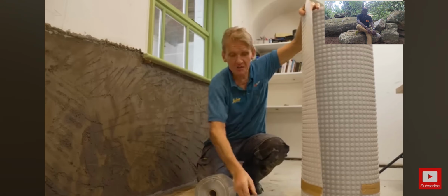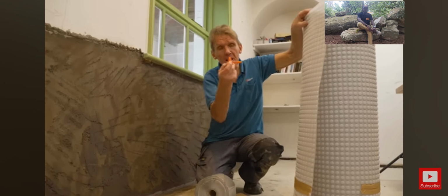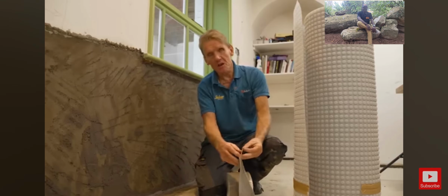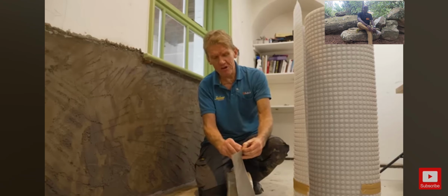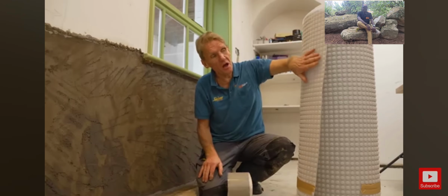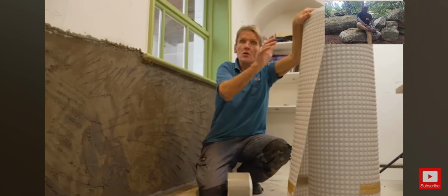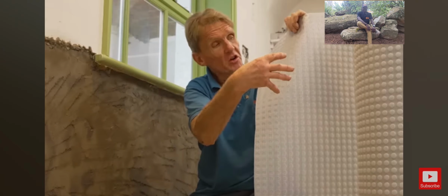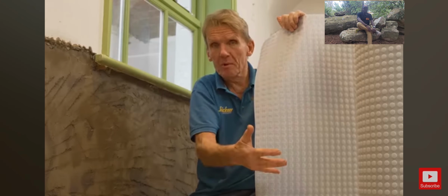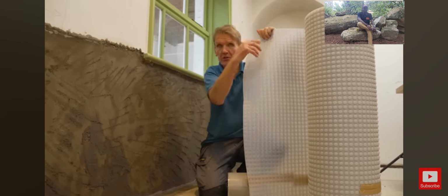But this is a great product, it's very easy to fix. You basically put it up against a wall, you drill the holes, plug the thing, and then when you come to do the joins, you use this self-adhesive tape which sticks incredibly well, and it has a fleecy back so that you can actually plaster over. Now, if you didn't want to plaster over, if you didn't want to put yourself a hardwall coat and then a finished coat of plaster on there, you can actually stud and dab on this membrane rather than a wet coat plaster. So some people prefer that because it's a lot cleaner and it's a lot quicker just to go around and dot and dab.